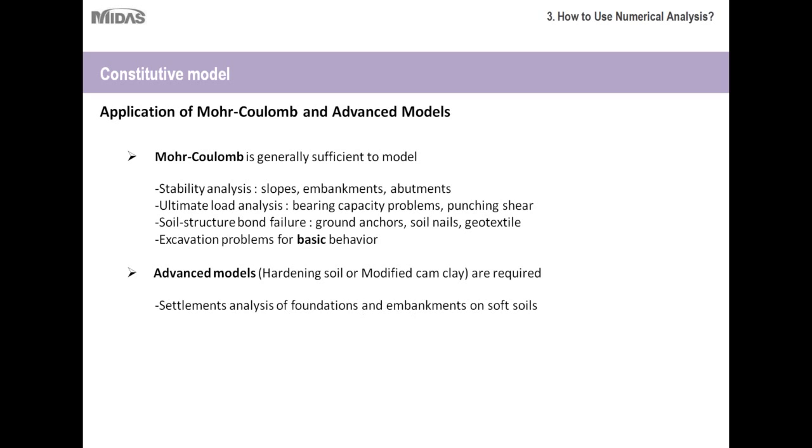So if you have a project that's located on clay saturated soil where you'd expect long-term drainage or long-term consolidation, then these advanced models would be used, just because there are certain parameters that the Mohr Coulomb doesn't take into account that need to be taken into account to realistically predict settlement over a long period of time. And then undrained or over-consolidated silts and clays, and then consolidation of soft soils.